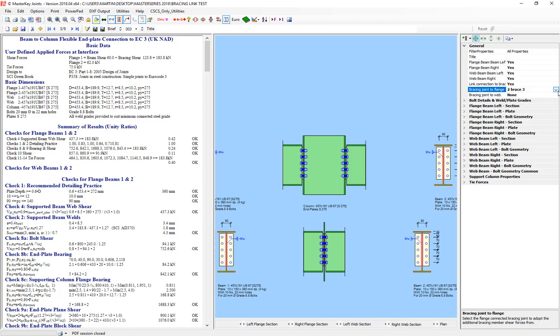In the case of an integrated design, you don't actually have to make that selection because it knows the actual reference point in the frame that the connections are linked to, and it automatically picks up the associated linked connection. So if you've got a linked simple connection and a linked brace coming into the same location, and you say you want to pick up the additional forces, because the additional forces themselves are obviously heavily dependent on the setting out of the braces and the geometry that gets produced from those.